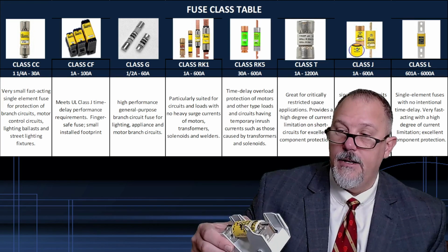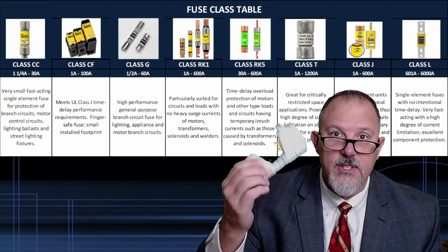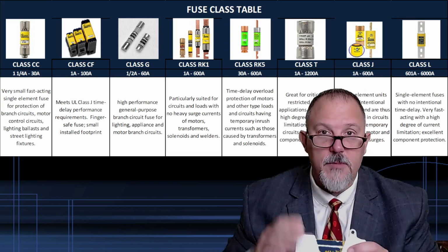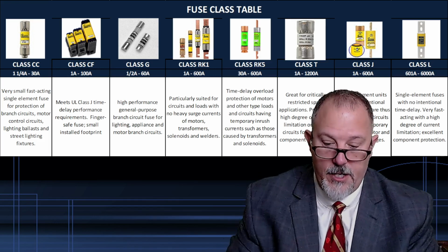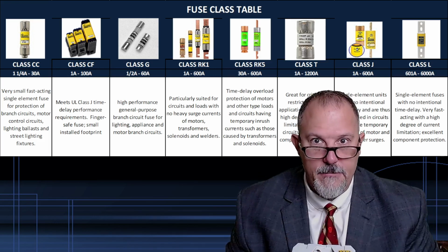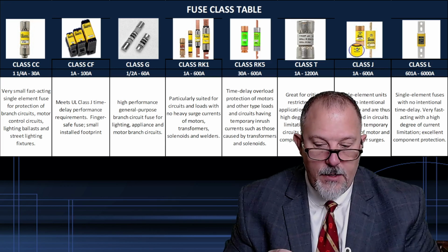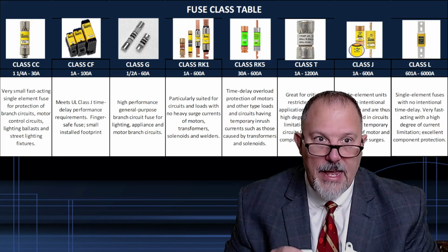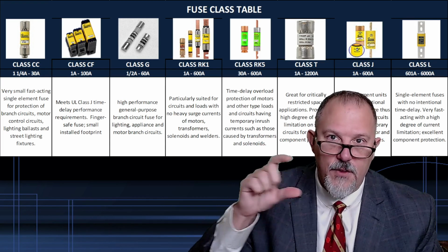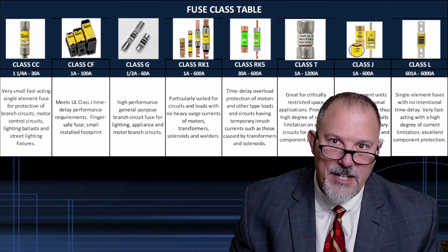This is a 100 amp fuse holder. I could put a 60 amp fuse in here. I could put something smaller, but I'm not going to put a 200 amp fuse in here. And how they do that is they manage the size of the fuses for each of those ranges.